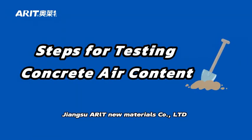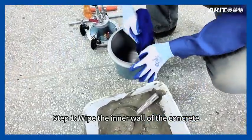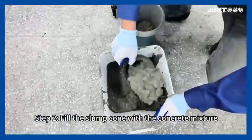Steps for testing concrete air content. Step 1. Wet the inner wall of the concrete air content tester container and the inner surface of the lid with a damp cloth.